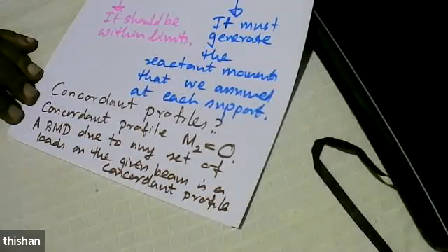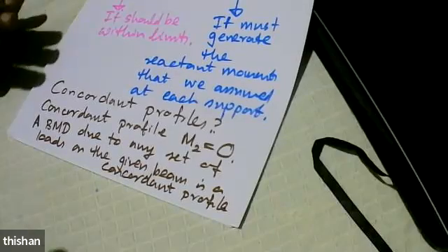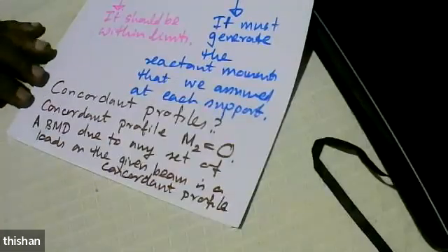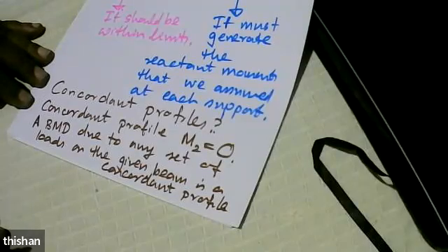And if you can fit that type of bending moment diagram into a zone, then it will generate 0 secondary moments. So what you have to understand is, if you fit a profile which actually represents a bending moment diagram due to a set of forces, it will generate 0 secondary moments.